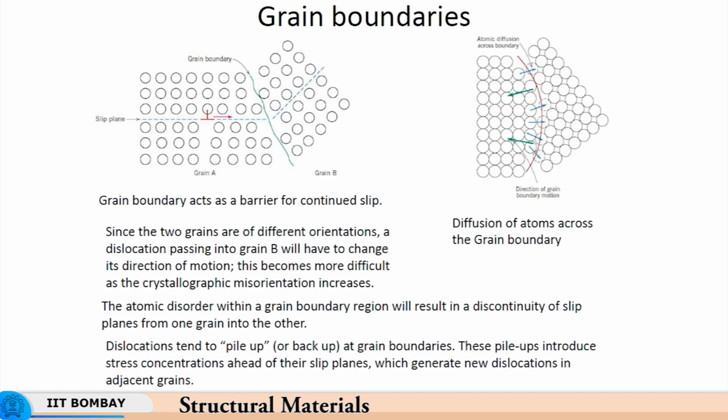So, the dislocations really do not move, because even before the stress needed for dislocation movement has been reached, the deformation in the grain boundary starts, because the grain boundary at high temperatures with all disorderly arrangement of atoms behaves like a viscous fluid. So, the grain boundary has characteristics of a viscous fluid, and that deformation in the grain boundary starts at a much lower shear stress as compared to what is needed for dislocation movement.